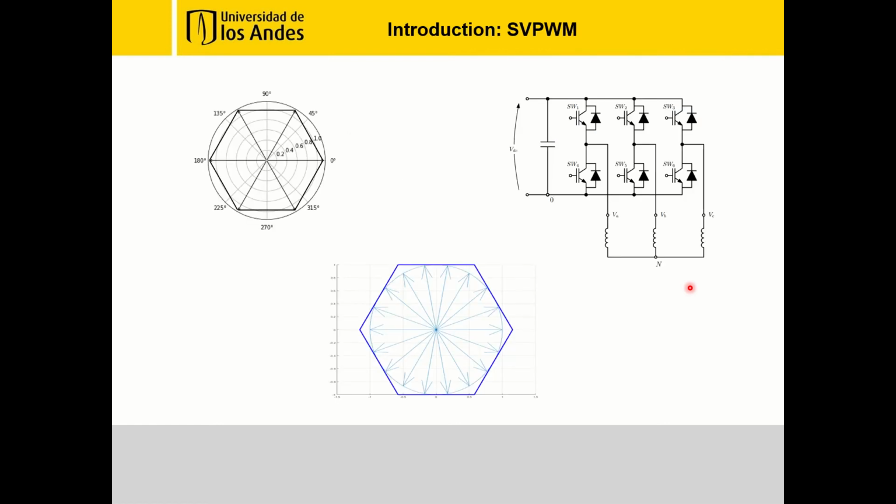The space vector pulse width modulation, or SVPWM, is a widely used method in inverter circuits to generate three-phase voltage. 6 switches are used to create 8 commutation states. Of the 6 switches, only 3 are controlled, the other ones do the opposite to avoid shorts in the system. This method of modulation consists of applying space voltage vectors during some fragment of time and in a specific order following a reference vector traveling within a circle.